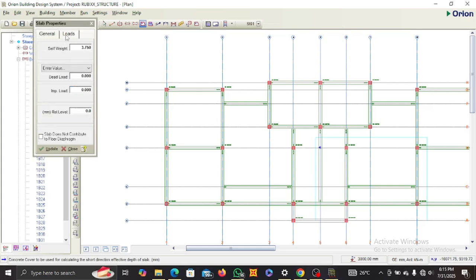So you come to loads, right, so it's going to be a room, so you can just click on enter value here, click, it's going to be a room, so it automatically generates the dead load for a room. It factors in the finishing and probably your furnitures for the dead load. Right, but then if you have a value already in mind, you can just click on enter value, then we can change this to probably 2 kilonewtons. But let's go with 2 kilonewtons. Or if you don't know, you can just click here, click on rooms, and you allow it to provide for you.